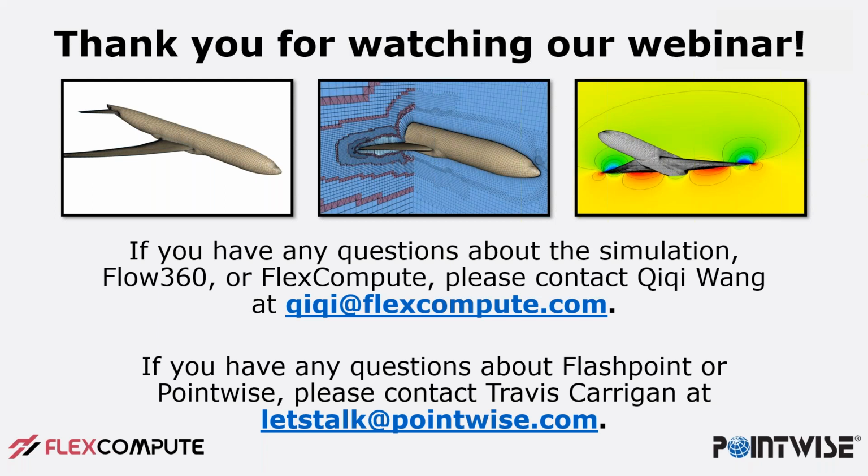And this is something that we've encountered: if you do some solid modeling operations and clean up your geometry, you may get to a point where there's a part of the geometry where you just cannot stitch it together. You can go ahead and apply the surface mesh on that and then just use grid merge to take care of that last little piece.